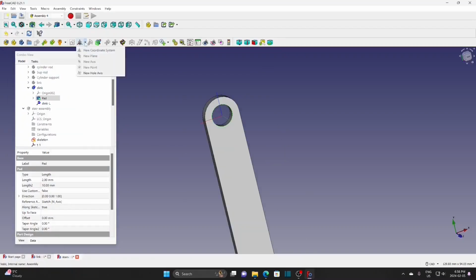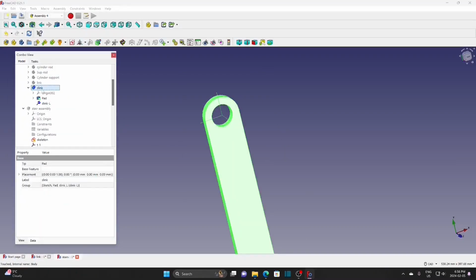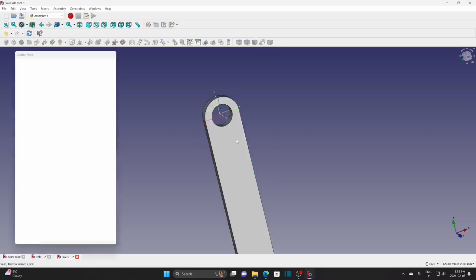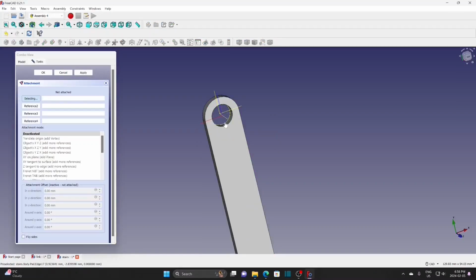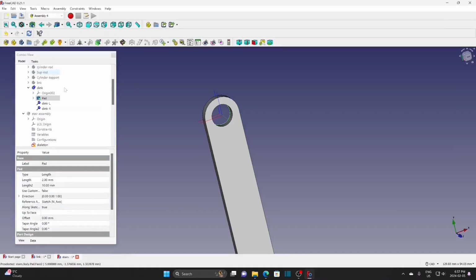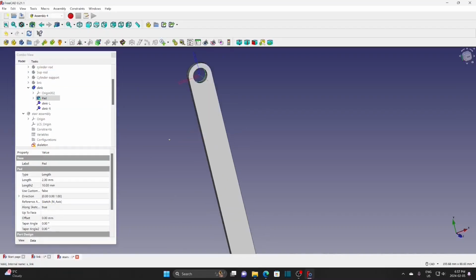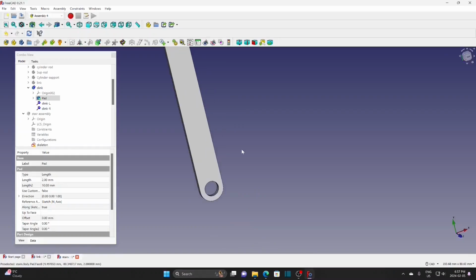Okay, another one. For the right hand side, select the bottom circle. Revolution, 180 degrees. So it matches the LCS on the skeleton sketch. Or you can rotate it and adjust it when you insert into the assembly. I usually adjust it before if I need to insert the item several times.